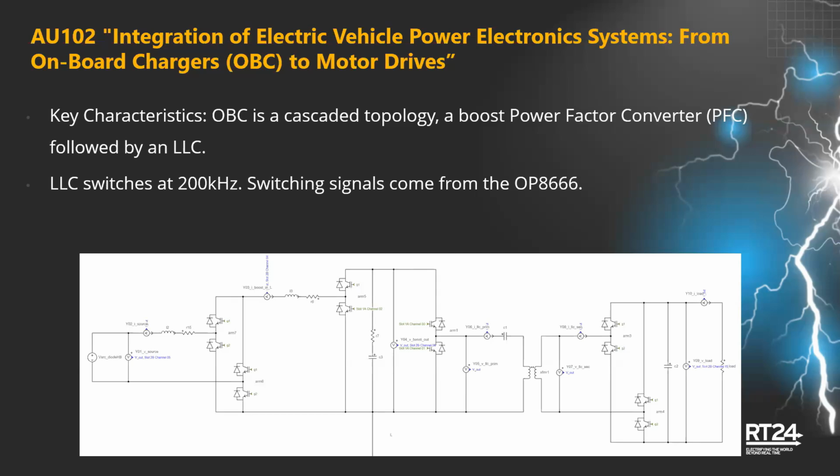That resistor effectively represents our battery, okay? So once we start our demo, we're going to charge up our battery to a sufficient level before we activate our motor. We need to ensure that our battery has at least an 80% state of charge, or SOC, before we can really begin running our motor.